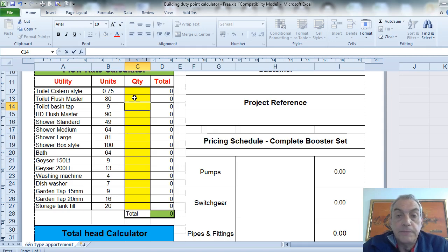Whereas a toilet cistern normally works on a float ball valve system. It's your common domestic toilet. You're sitting on a bowl. Behind you is a stored capacity of water in a cistern. You would pull the valve and the valve plug would open and dump between 7 and maybe 12 liters of water. Now, the fact that you've dumped 12 liters of water in a toilet cistern is irrelevant. What's relevant is the refill rate of that cistern. And that's what we're trying to determine here.